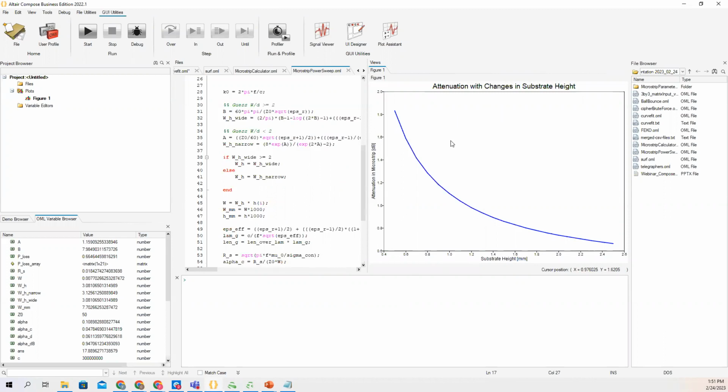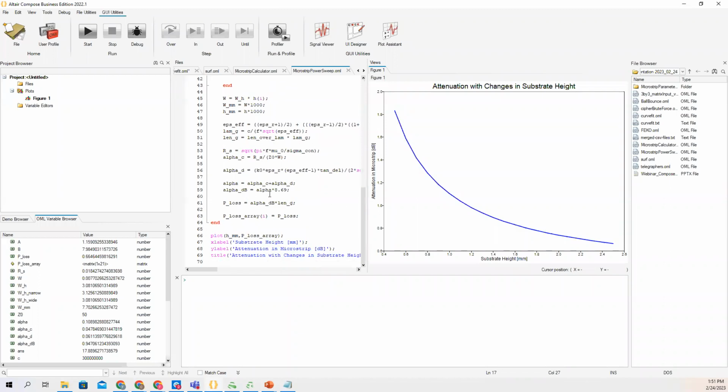As the height gets bigger, the width gets bigger, the width of the conductor, that is. So then we're looking at perhaps a different length of the actual microstrip. All these change the footprint, the mass, the cost of the device. And so let's say we wanted to actually optimize some of that.